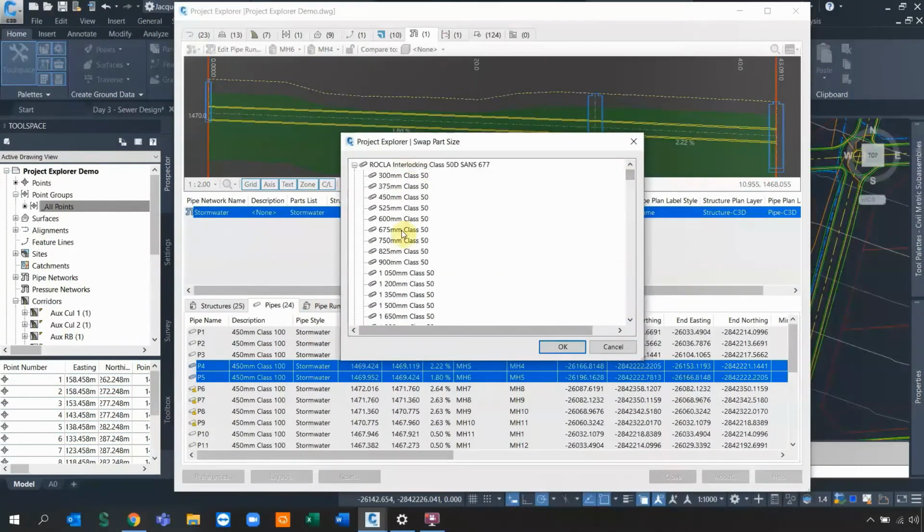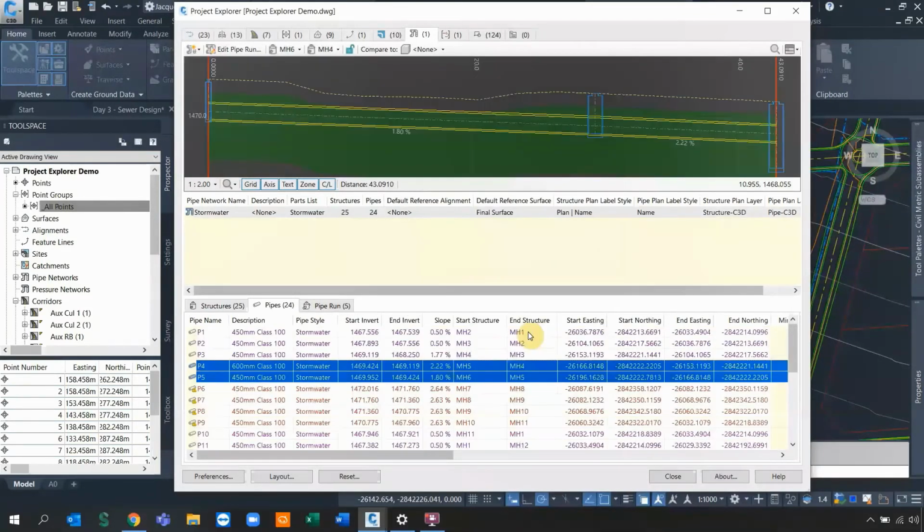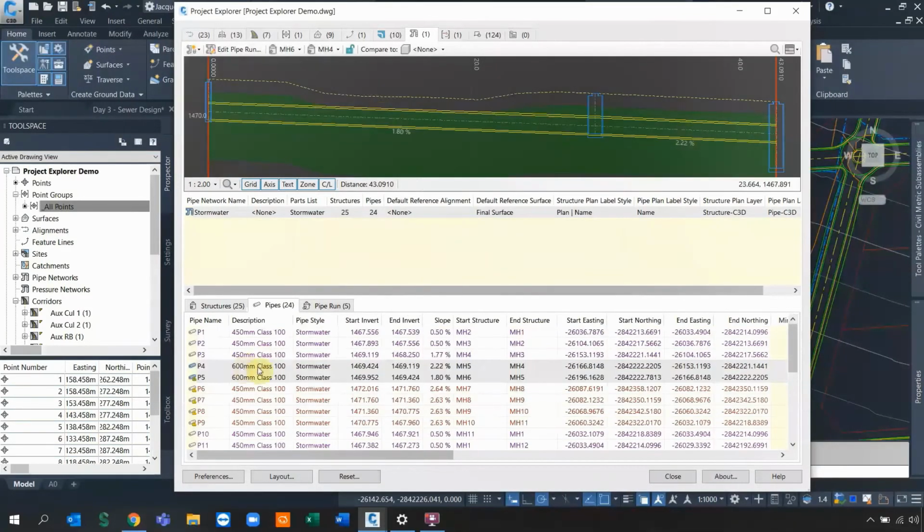of my catalog. So if I go to my catalog, let's change it to, I don't know, let's make it a little bit bigger. Let's say, okay, we wanted 600 mils. Bob's your uncle, boom, he swaps them out. Normally, you would have gone to each individual one and swapped them. From this location, you can swap multiple. Isn't that nice? That's really nice.